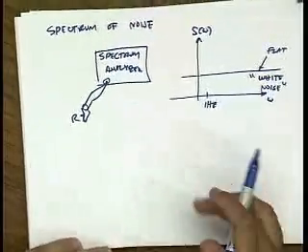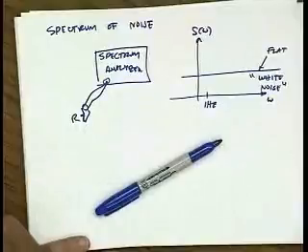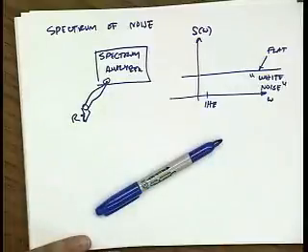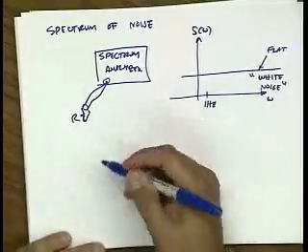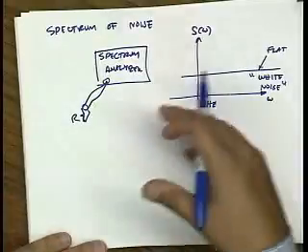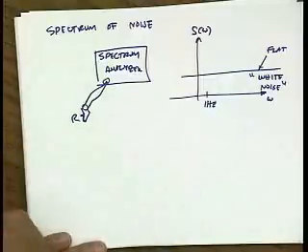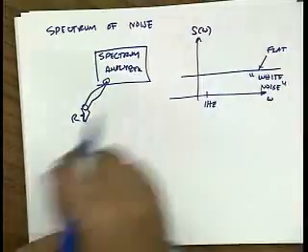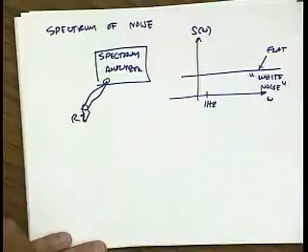Well, how many of you have taken 126 or an equivalent probability course? All right, so most of you know what we're talking about. For those of you who don't, don't be too intimidated. You will learn this stuff eventually. But you know that the spectrum really comes from taking a transform of the autocorrelation function. In other words, the spectrum is a measure of how correlated the signal is with itself. So if you have a flat spectrum, that means the autocorrelation function is a delta function, meaning the signal is only correlated to itself instantaneously.